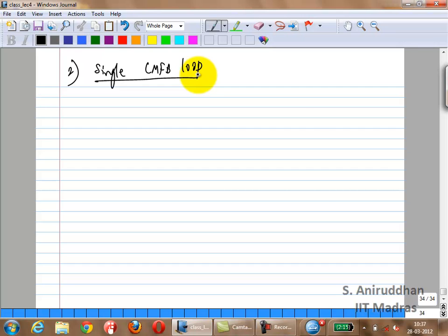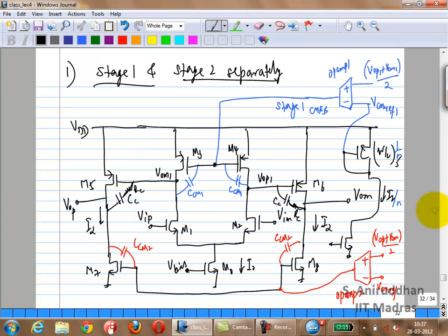That was fairly straightforward, right? You just do each thing separately for each stage. Well and good. You can decide that. You tell me what a phase margin affects. Settling time. You are worried about things like ringing. If you make a phase margin too large, it will take very long to settle. If you make it too small, it will start ringing. Eventually it will become unstable if your phase margin is less than 0. So settling time will decide how much phase margin you want. Typically you want at least 45; 60 would be a good phase margin. In most cases you would choose it to be 60 degrees.